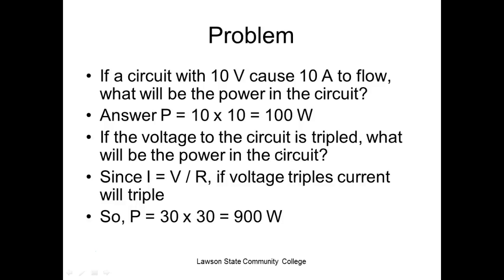We do a circuit in motor controls where we simulate multiple loads in series. In motor controls, you can't put multiple loads in series. I don't know if you've had motor controls or not, but we have a light bulb up there and it's dropping voltage and it doesn't even come on. I've had people say, well, there's something wrong, this light bulb's not coming on. Well, what's the problem? We got three loads in series.